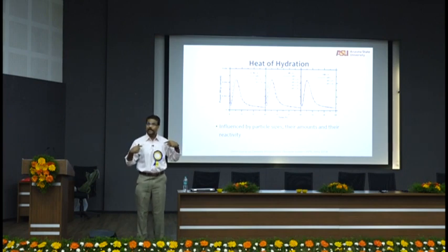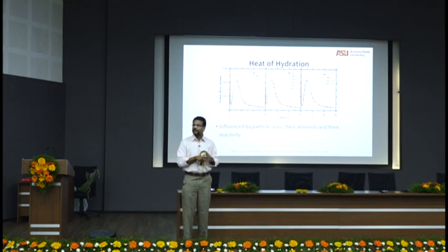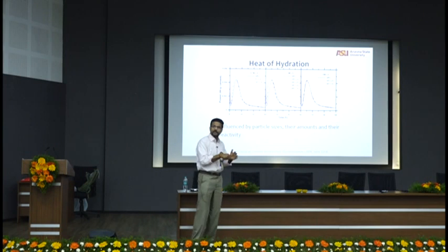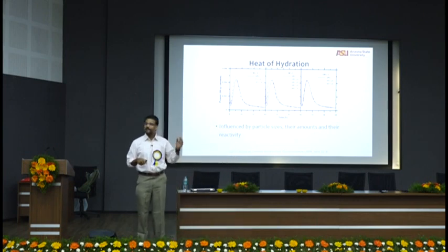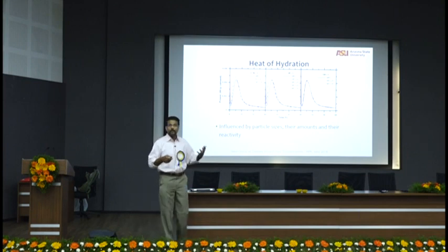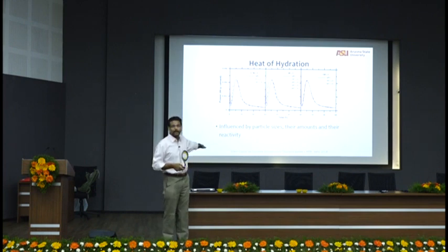I've been told by Grasim when I was working, get our cement content to at least 450, while I was fighting for 350. I was told we want this concrete to have 450 kilograms per meter cube. I said I can get it at 350. Doesn't matter, our cement, we need to sell cement. Right? So as long as you have prescriptive specifications, this will not happen.